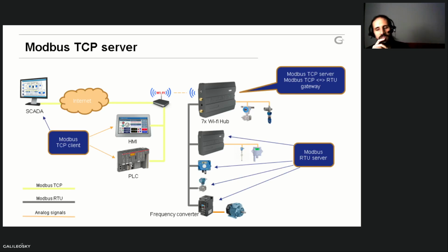What's new about this feature? Our devices, using this new script that we developed, can get data from RTU, as you can see here, connected to different devices that work as Modbus RTU servers, and get that data and send it to the Modbus TCP server.